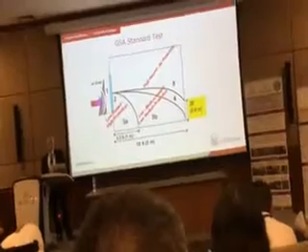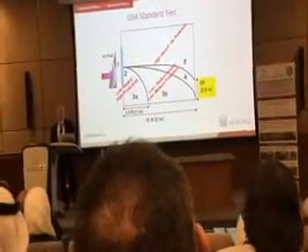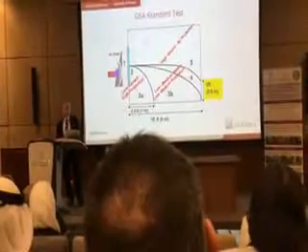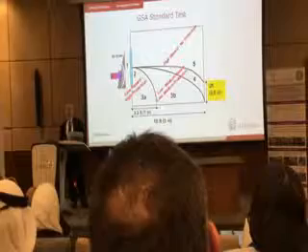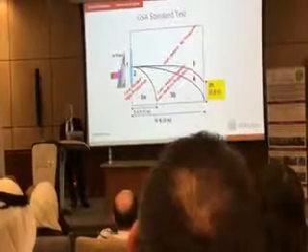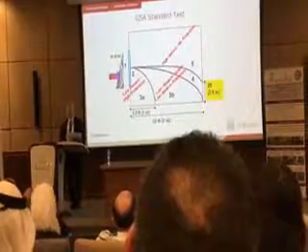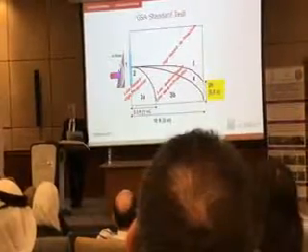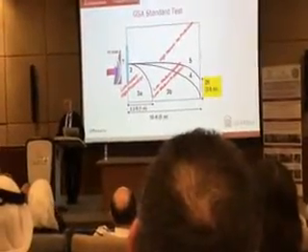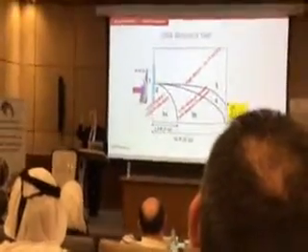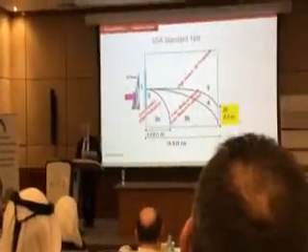if fragments fall within 1 meter, it is a very low hazard or high protection window. If the fragments go all the way to 3 meters, then it is low to medium. If it goes past this 3-meter distance, and this is a witness panel, it's a styrofoam wall, and those glass fragments go and get stuck on the styrofoam, and you have to weigh them.